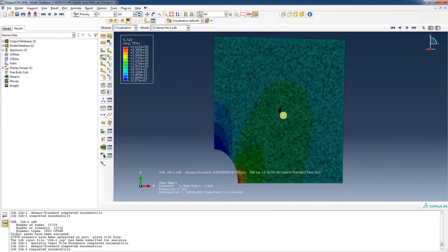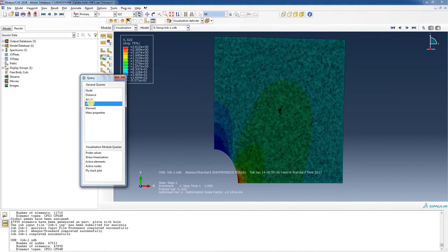It looks very dense in here. That's kind of a weird auto-meshing algorithm. You can kind of see that it has a spot that it likes, and then it builds the mesh around it. There's some very sophisticated auto-meshing algorithms. All right, so this one says 2.612. And let's go and query the mesh and see how many elements we have now. 47,890.